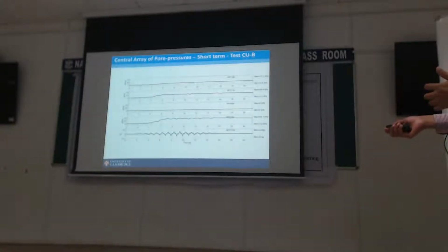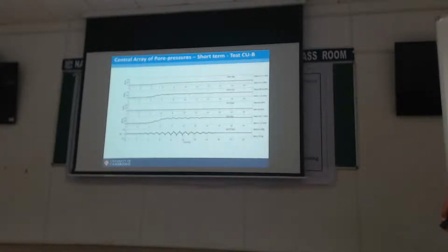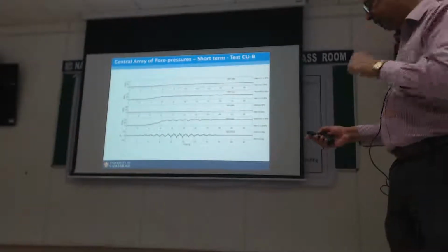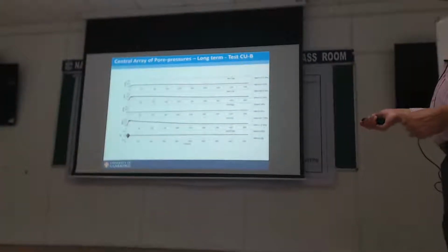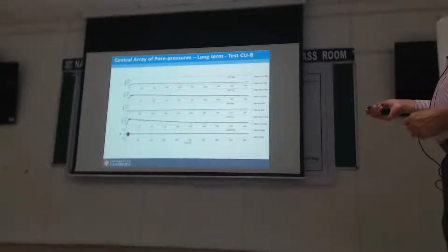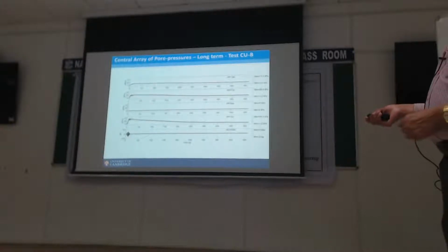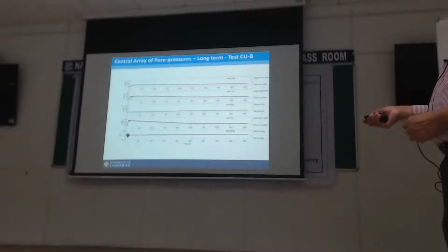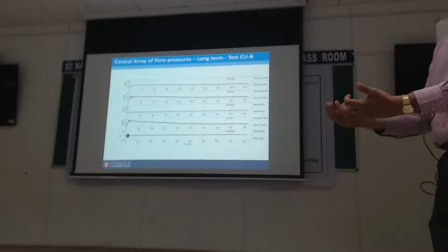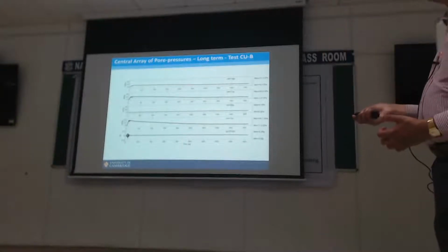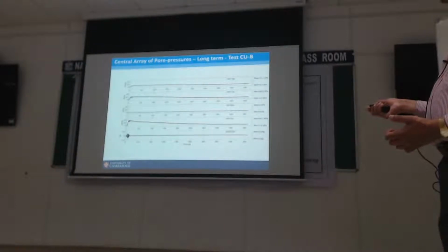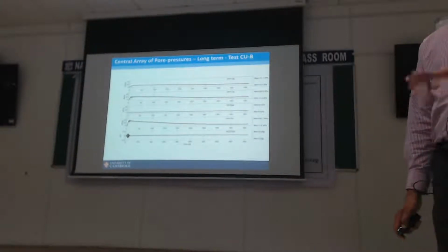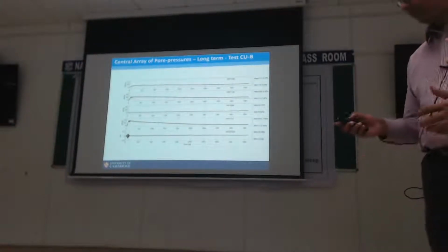That I'm showing during the shaking for 0 to 20 seconds. If I plot long term up to say 450 seconds or something, then you can see how long the pore pressures are taking to dissipate. So the base one starts to dissipate first because all the fluid is trying to go up, and this fluid coming from below keeps this liquefied longer and even longer at the surface. So physically, it's all consistent.